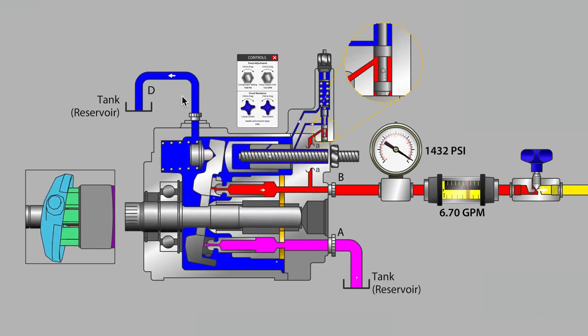If you're familiar with the principle of a fixed orifice in a hydraulic system, anytime you increase the pressure on the inlet side of that orifice, the flow rate through that orifice will increase. So inside of a piston pump with all of the moving pieces, there are clearances, for instance, between the piston and the cylinder in the cylinder barrel. And remember, there's 7 or 9 of those, so there's clearances there. There's typically a bit of clearance on the back of the slipper pads, or piston shoes as they're sometimes called.